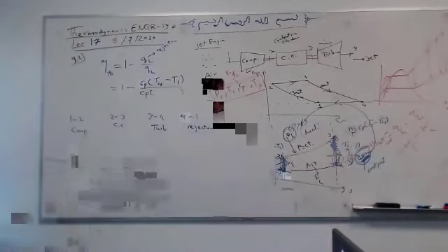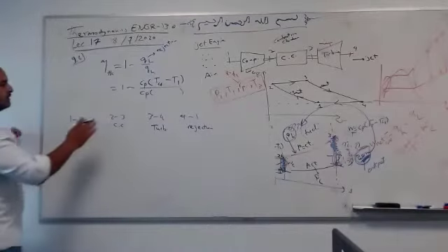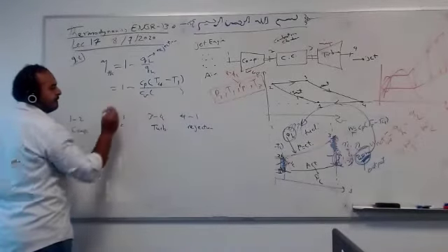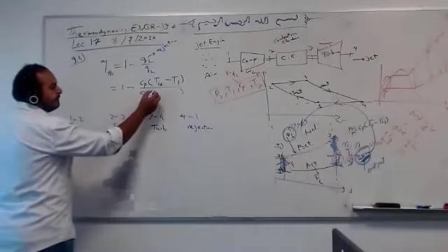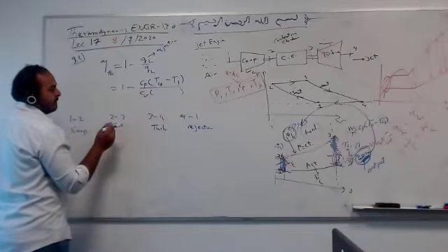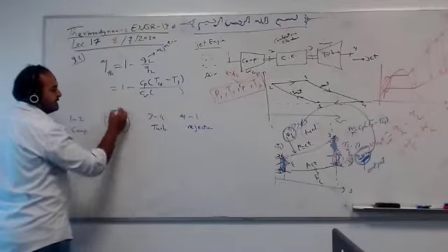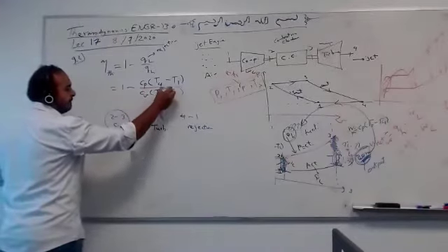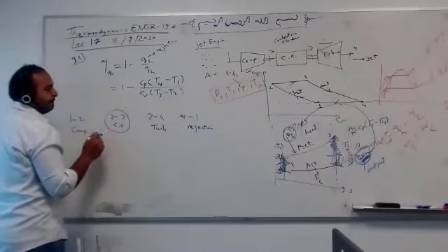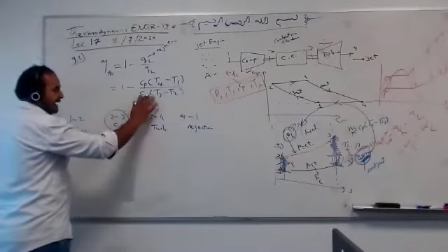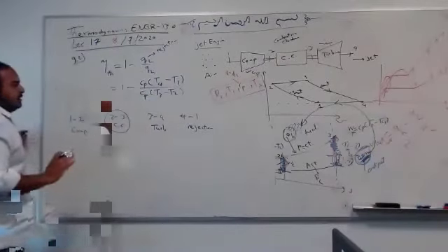Somebody tell me what is Q high? Heat addition between 2 and 3. Is it CP or CV? It should be CP, right? Exactly. Everything is delta H, so CP. Be confident.